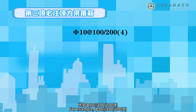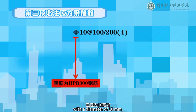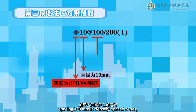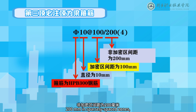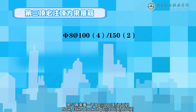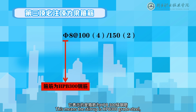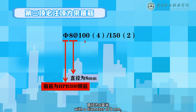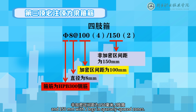For example, Phi 10 at 100/200 means that the stirrup is HPB 300 grade rebar with a diameter of 10 mm, spacing 100 mm in densely spaced zones, 200 mm in sparsely spaced zones, and 4-leg stirrups throughout. Now, take a look at Phi 8 at 100/150. This means the stirrup is HPB 300 grade steel, with a diameter of 8 mm, spacing 100 mm and 4 legs in densely spaced zones, and 150 mm with 2 legs in sparsely spaced zones.